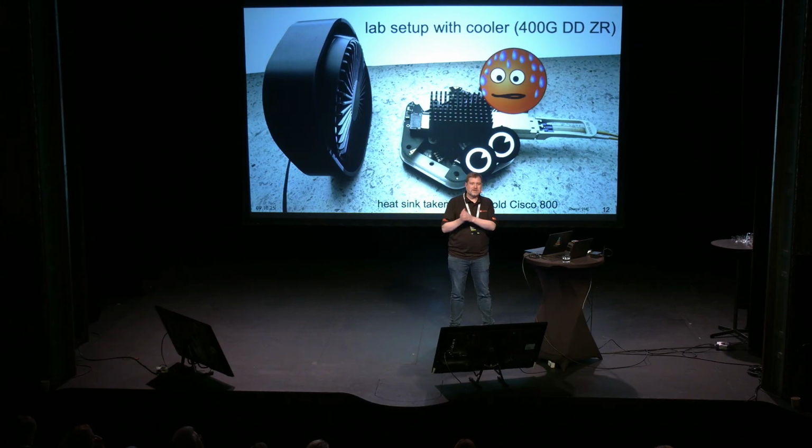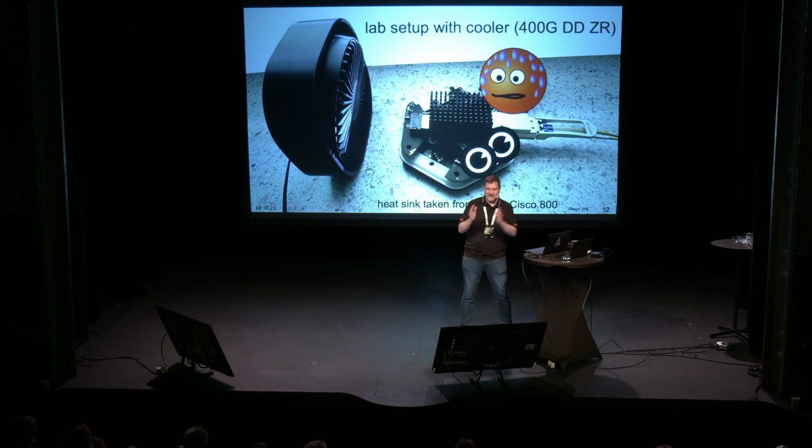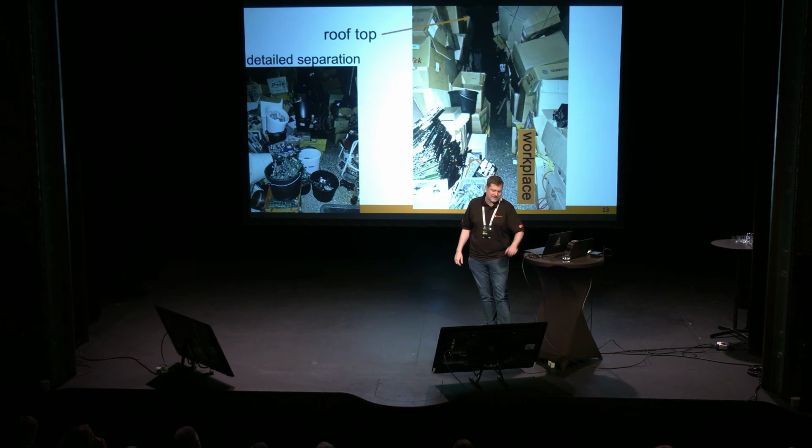You don't look at an eye diagram. You could do it, but you would have to split it up. It's a little bit more complex, so that is the difference of these technologies. But the advantage of more complexity also means you can transfer more data at the same baud rate. It also means that these get way hotter than the direct detection transceivers.